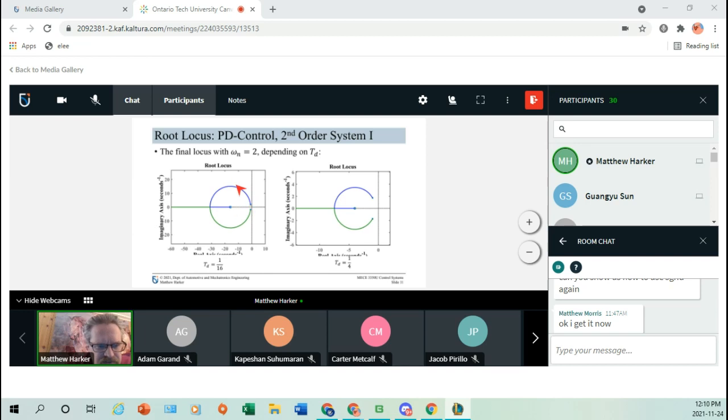So you can see this circle now has a relatively large radius. And what the zero has essentially done is pulled the root locus down away from the imaginary axis and wrapped it around, so that we have one locus going around to that double point, and then back to our zero, and the other one going around to the double point and then off to infinity.